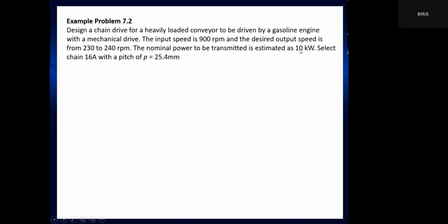P is 10. Select chain 80A series with a pitch P of 25.4 millimeters, and then design the chain drive according to the design procedures.